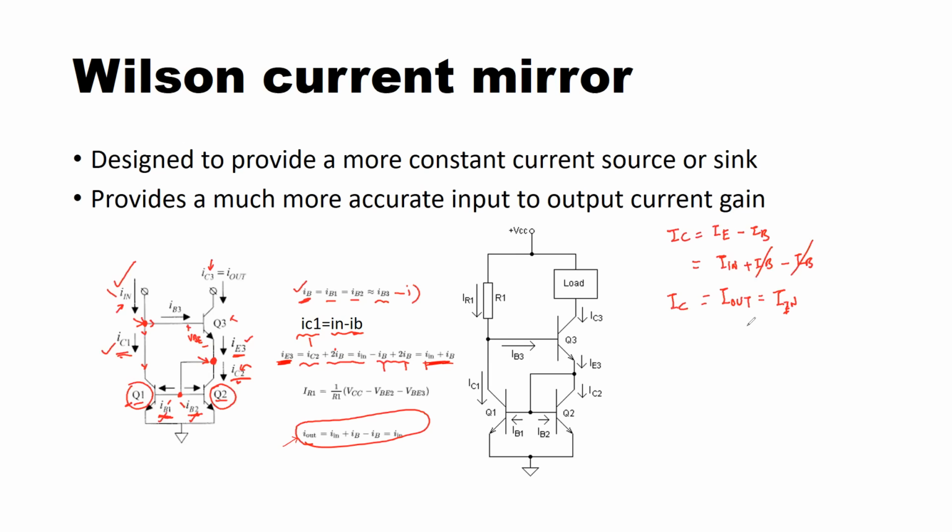So you see the static error on the first order is removed. But if we do a more thorough analysis of this circuit, then we should get an expression involving the transistor current gain, as I can write here with this equation right here. So the difference between the two currents, that is input current and output current, is still there, and can finally be written as 2 times I in divided by beta.